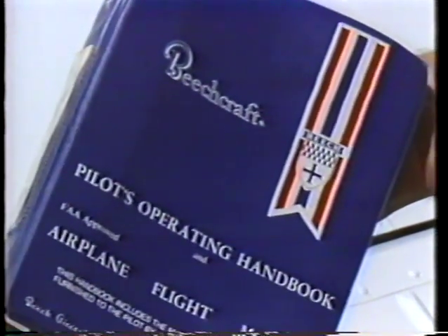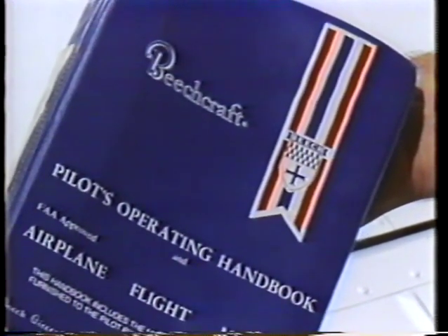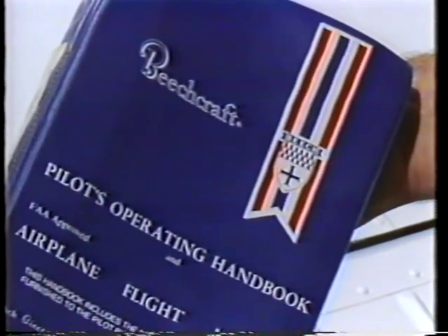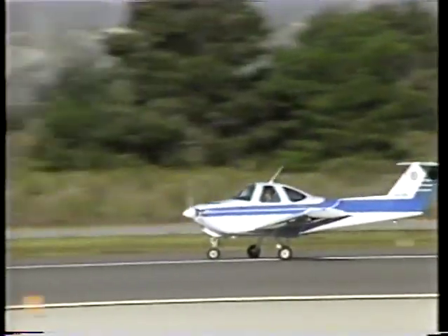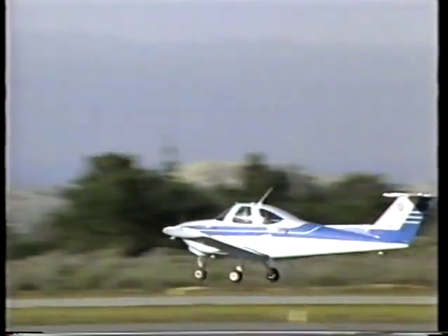All the information and the solutions to the problems are found from tables in the pilot's operating handbook. For this problem, let's use the Skipper that Jeannie and I have used for most of our lessons. If we refer to the pilot's operating handbook and weight and balance papers that are maintained and kept aboard the airplane, we will have no difficulty locating all the facts we need for the tabular approach to weight and balance. First, let's use this worksheet for recording our data.